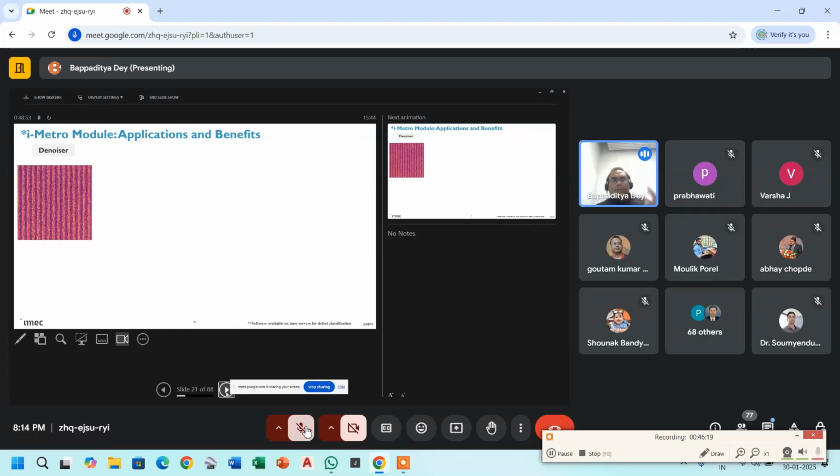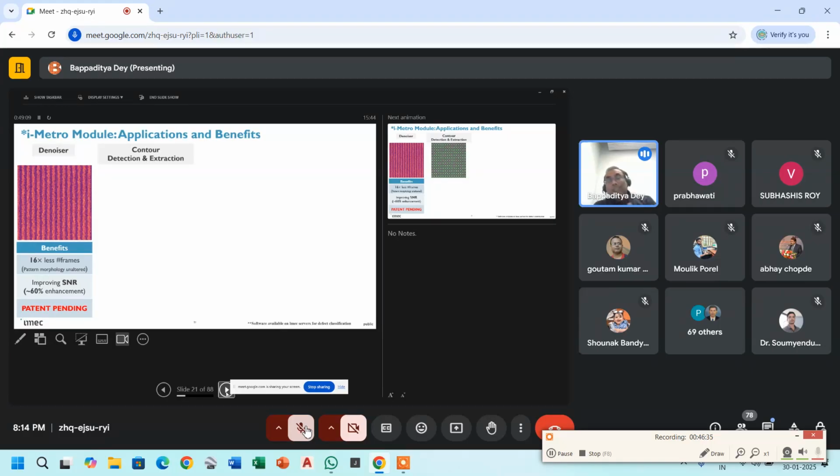So some of the applications, and we can see that for the denoiser, we are denoising it, right? And not only that one, this module is also helping you with the other constraint, as you can see here. This is an industry standard that you generally require 64 frames of integration at least to extract all the information from these images. These are metal lines, and metal lines have a spec, so you can extract all this information. What you have printed is basically from 64 frames of integration.